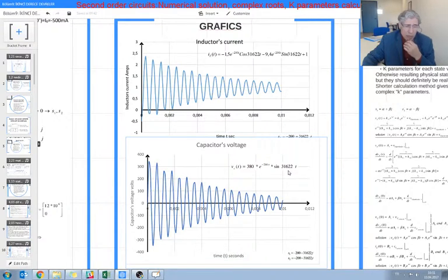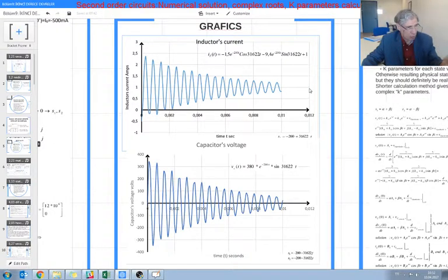So if you do it for the inductor, you're going to end up with a function like that. In this function, you see there is a particular solution here. You can check this particular solution. After 20 milliseconds, this transient solution, which is the homogeneous part of our general solution, is going to disappear, and we will be observing only the particular solution.